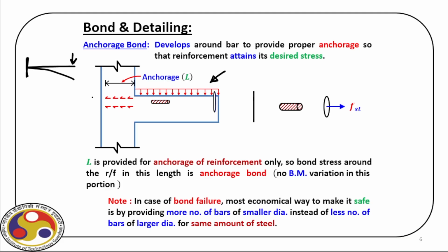Now when we provide rebars, obviously if this is the column face, then the top face is under tension, and therefore the main rebars against flexure we should provide on this face. Now the question that we are going to answer is whether we stop these rebars here at the face of the column or it should go beyond. Because we need proper anchorage, we have to go beyond. If we provide rebars only from here, there may be a slip and it may fail.